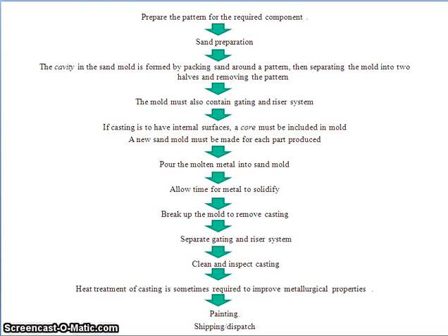After pouring the molten metal into the mold cavity, it is allowed to cool so that it will solidify. After solidification of the casting, the same mold box is placed upon the vibratory platform, which is also known as the shakeout unit, where the sand which has been sticking to the casting surface disintegrates and falls down, and only the casting remains on the vibratory platform. Now the next process is to remove the unwanted parts, which is nothing but the gating system, from the casting, and this process is accomplished in the fettling section. The fettling section removes the runner, riser, gating and unwanted parts from the casting, and it is finally finished by using a grinding operation.